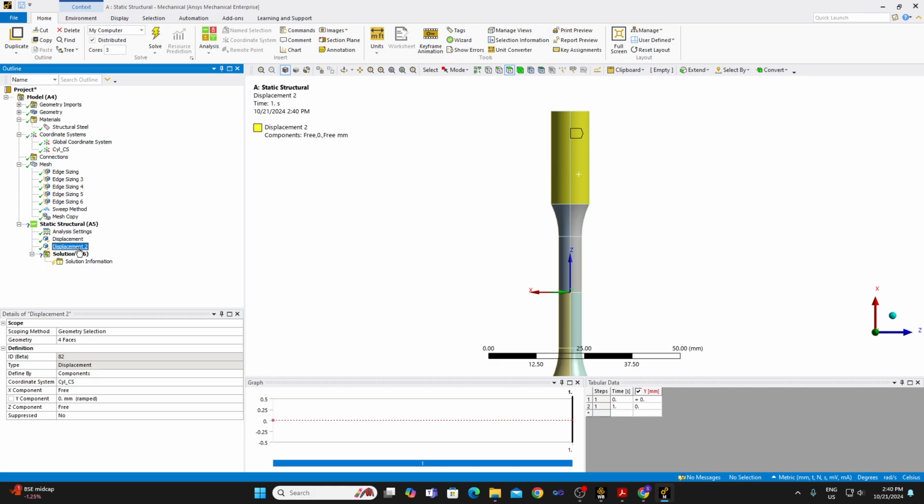Okay, we are applying no boundary condition in X direction, but X direction is here only the radial direction. So radially the specimen should be allowed to expand or compress. As you elongate a specimen, it is supposed to have a lateral compression, and that is only possible when the lateral surface is free from lateral constraint, which means you are pulling it along the axial direction, but its lateral surface is free to compress. That's how the lateral contraction can happen. So no constraint in X direction would be given.